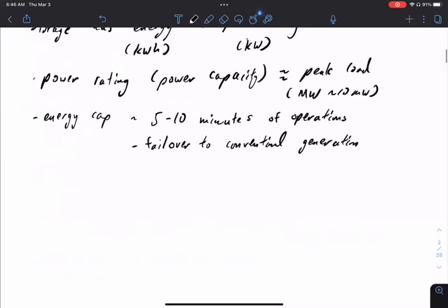So next, think about if you have a data center, where would you put the battery? What this battery looks like for traditional data centers is you have power coming in, so this is the grid coming in. You have a UPS, right? This is your battery, basically an uninterruptible power supply. Once the grid comes in, it charges the battery. The battery sits within this UPS. This goes to the rest of the data center.